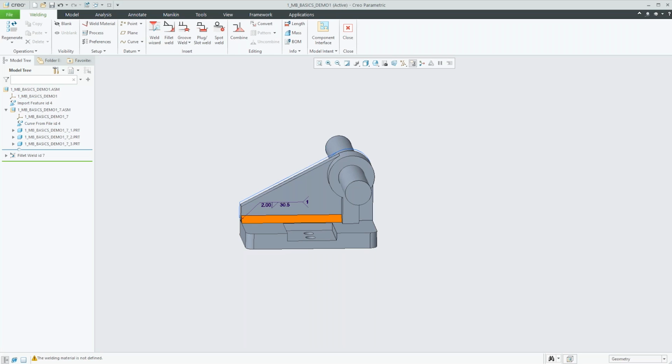It comes in as an assembly, as we saw, if it's separate bodies. Or you could extract each one of those as separate parts and then reassemble them, which would be kind of a lot of work. I'm thinking almost STEP out and STEP it back in. You get a STEP assembly that way, and then you can start working with the individual parts. Maybe that might be the most efficient way of doing it.